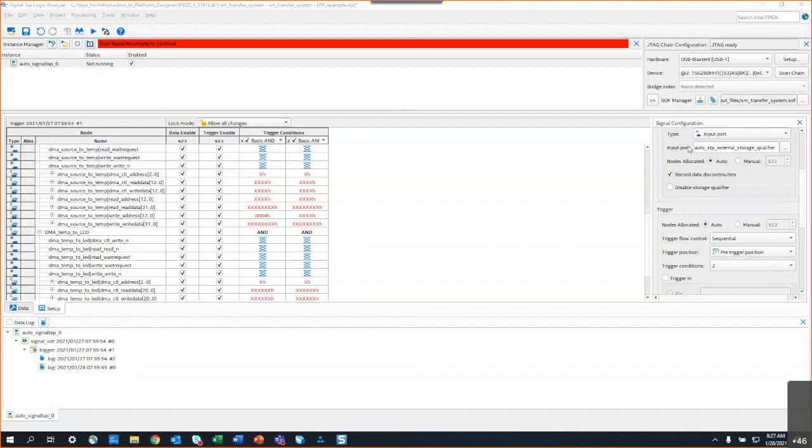One of the things to be aware of with Signal Tap, and I think people sometimes forget this, is that Signal Tap is great. I love it. I'm giving an office hours about it. The problem is that anytime you add a stub on any wire, which of course is what you're doing when you're adding Signal Tap to your design, you're adding another branch off of your signal, that can affect timing in your design. So, of course, when you're finished with your design and you've debugged it and everything, you remove Signal Tap. You don't leave that logic in your design. So it's entirely possible, unfortunately, that Signal Tap could potentially affect the timing on your design a little bit.